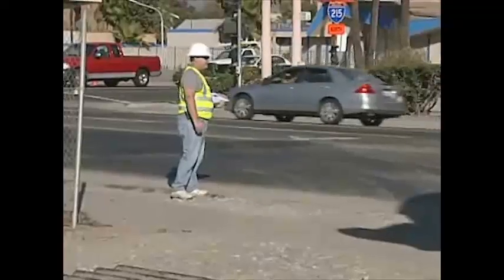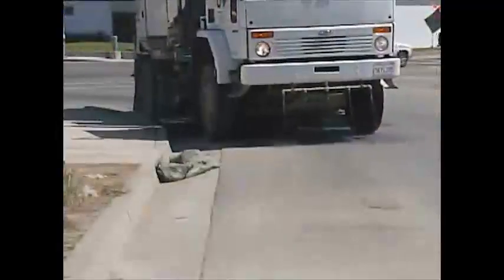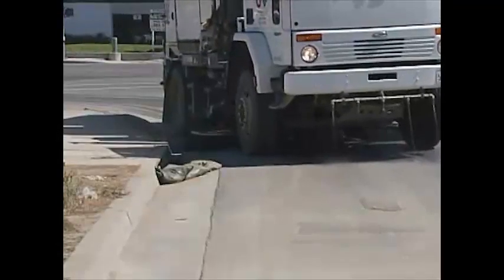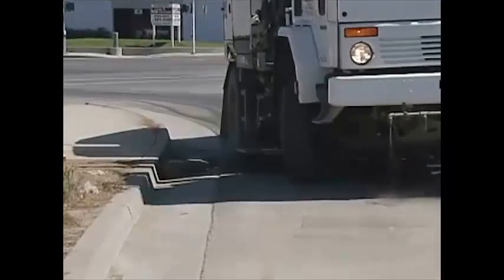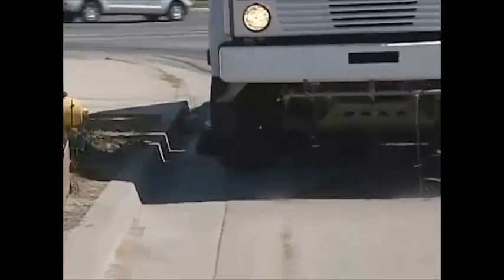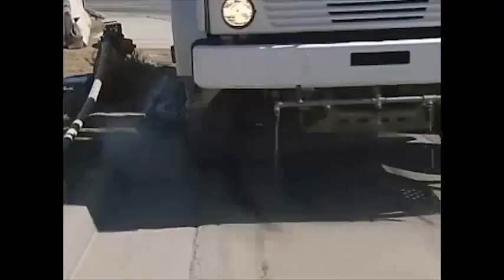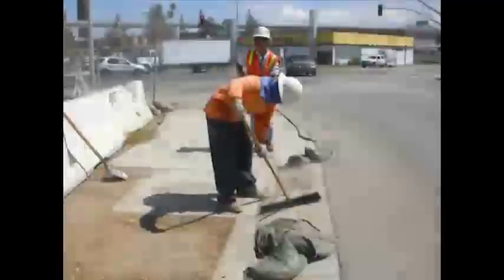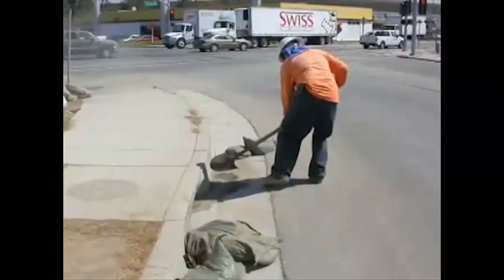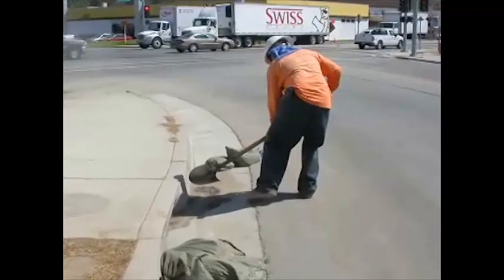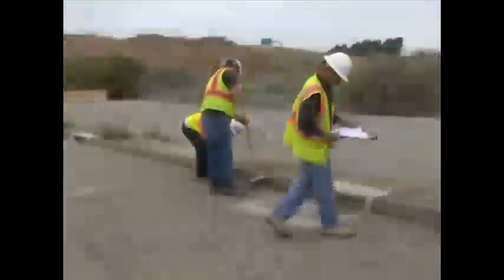Check to make sure that there is no tracking of sediment or rocks onto the paved roadway. Also check that sweeping is being performed at an appropriate frequency. Caltrans requires the pavement be cleaned and sediment removed at least once a day while the temporary entrance is in use, or as often as necessary, as determined by the resident engineer. Check to determine whether soil and sediment or other materials tracked onto the existing pavement are entering drainage facilities. Implement the appropriate BMPs if necessary.